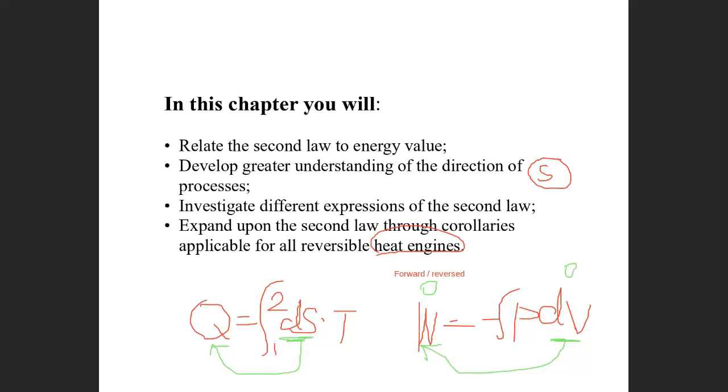If for a system the change of entropy is 0, like for an isentropic process, then there's no heat flow. That's what we have learned. And we have further learned on the temperature-entropy diagram that for a heating or cooling process, the shaded area below the process line is the heat flow. This is what we have learned today.